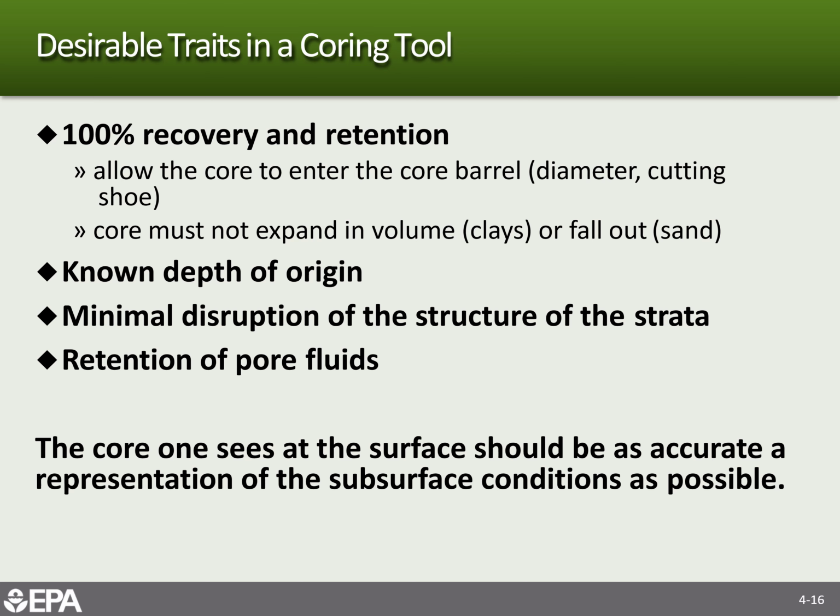You have to know exactly what depth it's from, which requires coordination with your drillers so that you really understand how deep that sample is from, because you're going to need to correlate that with the ones from other parts. Plus, you need to be specific about the depth to more than the foot, hopefully to the 100th of a foot, because sometimes that makes a difference.